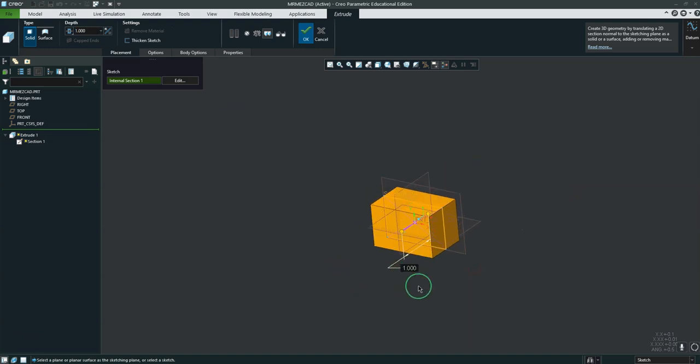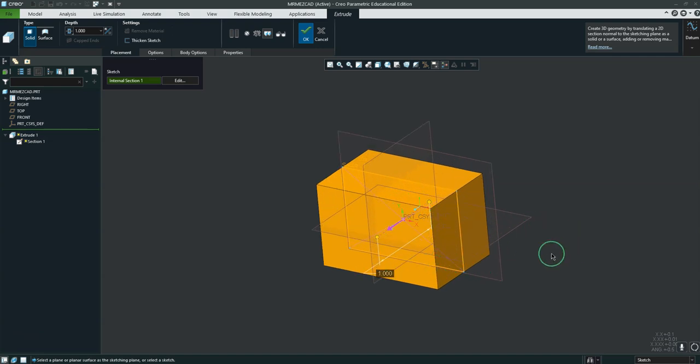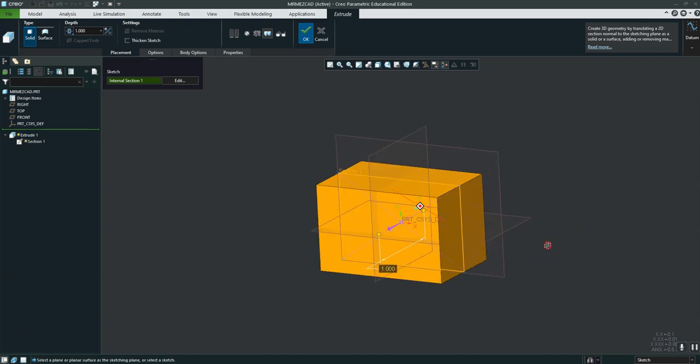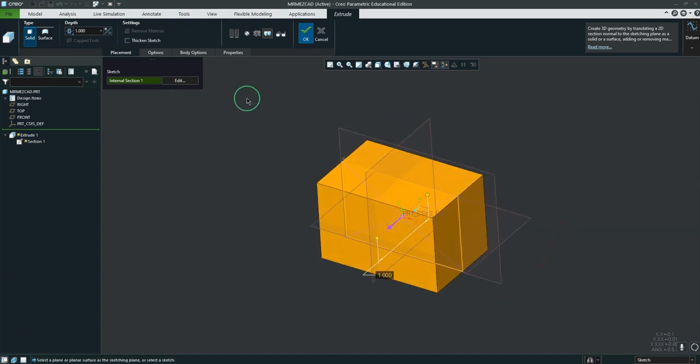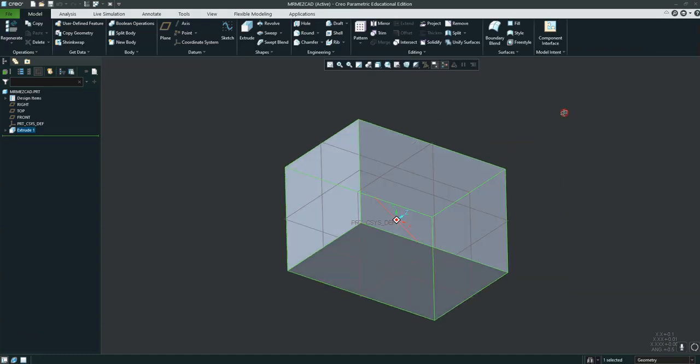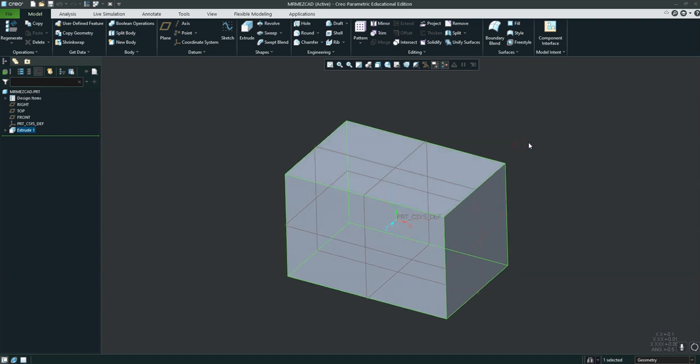Okay, now to rotate my block, I'm clicking the middle mouse button but holding it down and dragging. That's what I have my settings set to, and that's the default in Creo. All right, so now I can hit the checkbox, and I have a solid block. This is the main extrusion, the main mass of my two-sided die. Now we're going to turn it into a two-sided die.